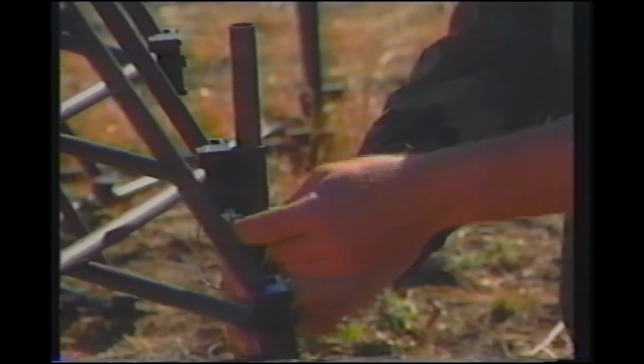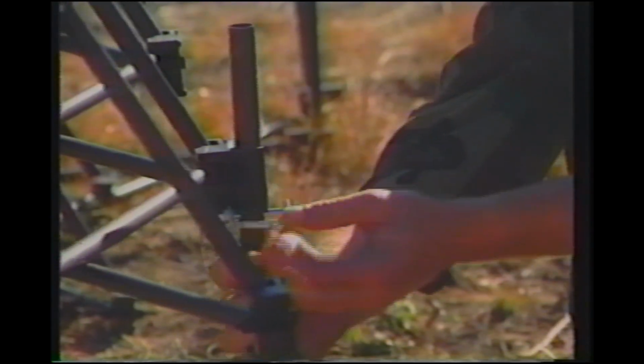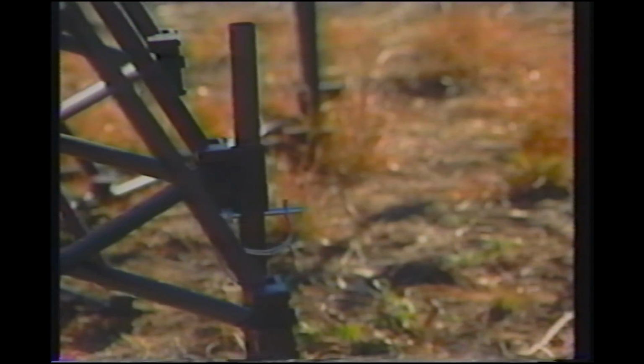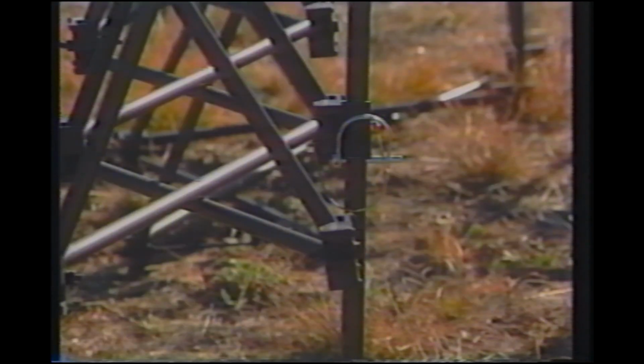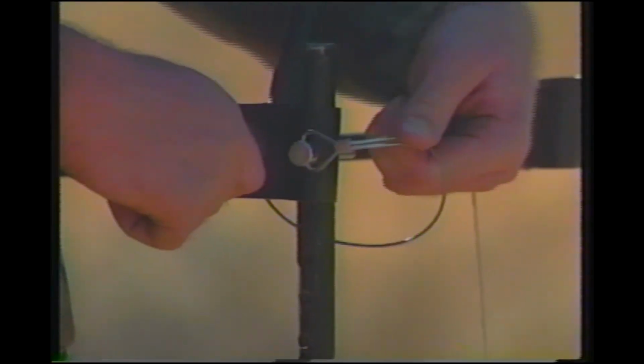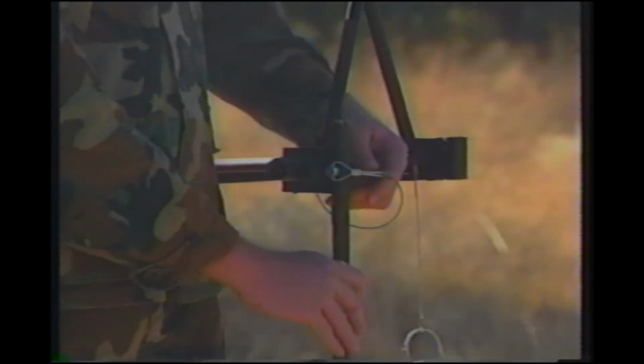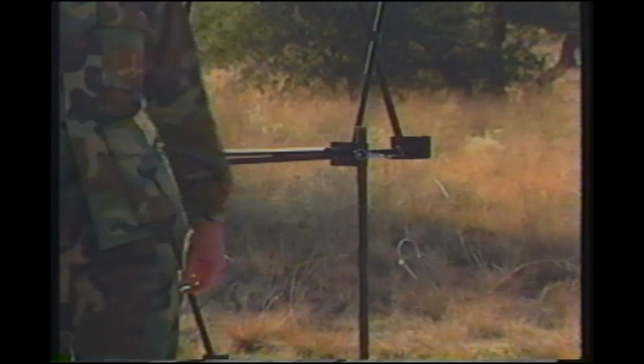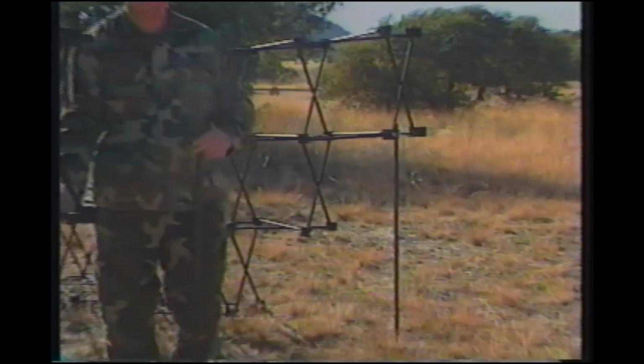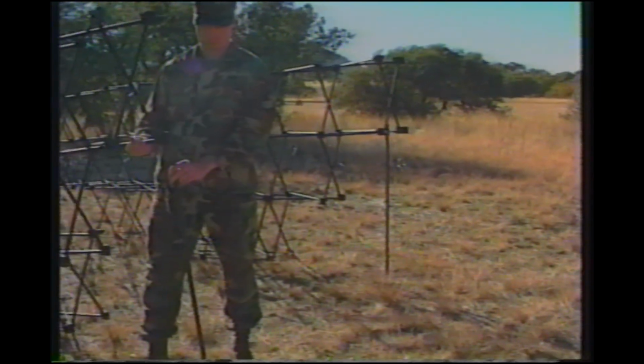Level the front frame and slide the safety snap pin through the support leg below the frame collar. Secure it with the spring wire. Now, position the 2 long support legs in the L-shaped frame collars located at the rear inside corners of the side frames. Level the side frames.